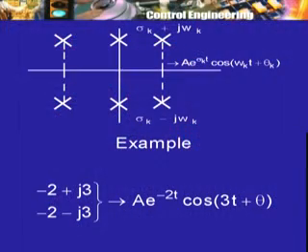But poles in the left half plane, whether they are real, lying on the negative real axis as it is called, or complex and lying in the left half of the complex plane, they are all okay, and they would cause either oscillatory behavior which is damped or simply exponentially decaying behavior. Moreover, one can find out the time constant of the exponential decay by knowing the locations of the poles.